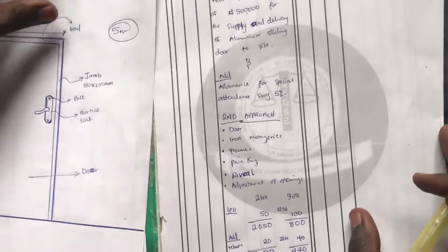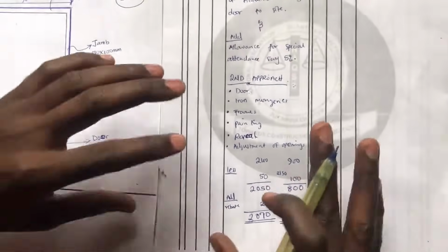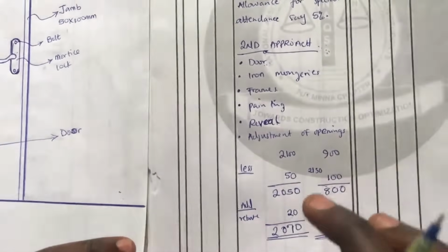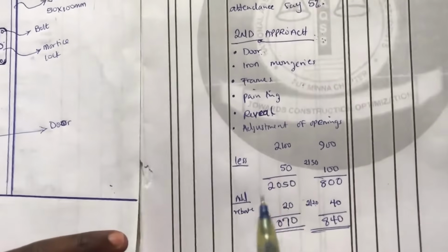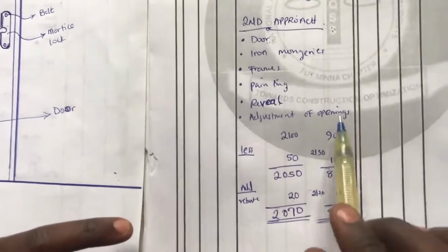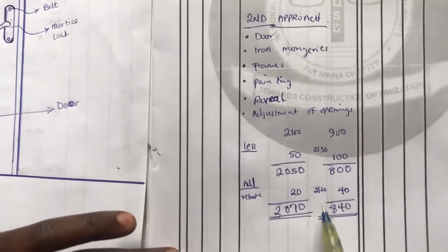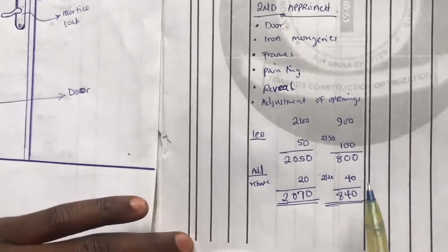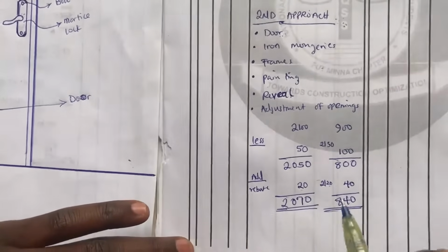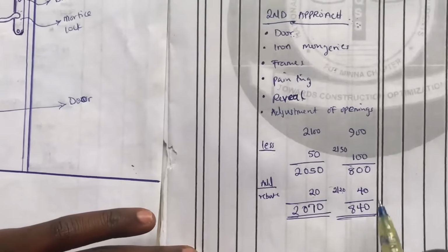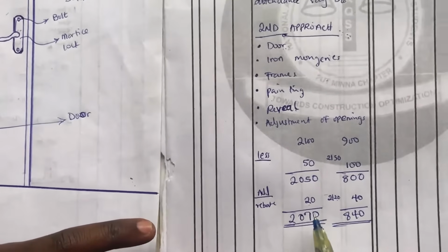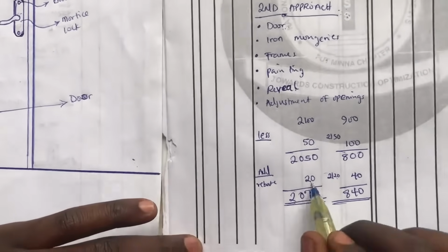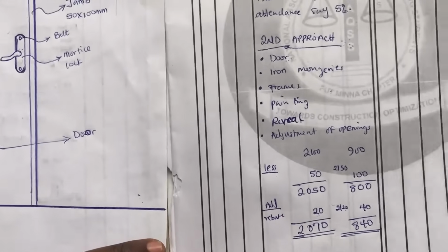So I urge you that if you are having an examination on doors, please, first thing to do, carry out this calculation. Just get the dimension of your door as stated, then less the jamb and the head from the height and the length as I have done, and add the rebate, except if your door is not rebated. If you are studying in the Federal University of Technology, Minna, in Nigeria, just know that you would always need to add this rebate, except if it is stated otherwise. So always remember to add it, and your rebate is not restricted to 20. It can be 10, it can be 20, but I urge you to be sensible in what you do and also state whatsoever you are adding for clarification.